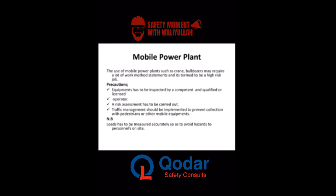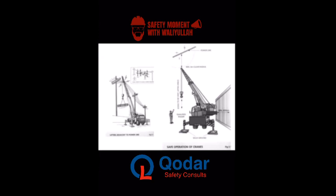When doing a task or any form of construction with this equipment, it is advisable that we do our work in line with the method statement that is being provided for this job. That is, the equipment has to be inspected, a risk assessment has to be carried out, and the load has to be accurately measured so that it doesn't become a hazard to those persons on site. To my left is one of the power plants here. That is a machine here, a crane rather, trying to lift a load against an overhead power line.